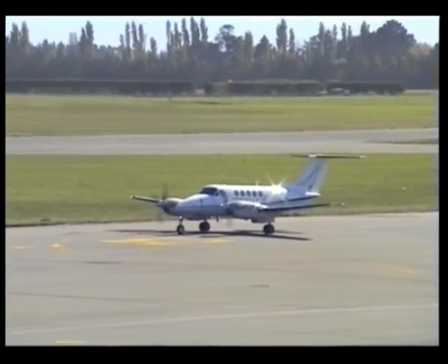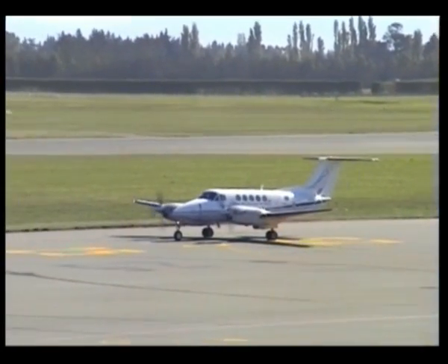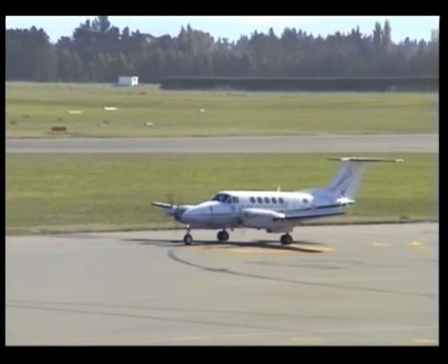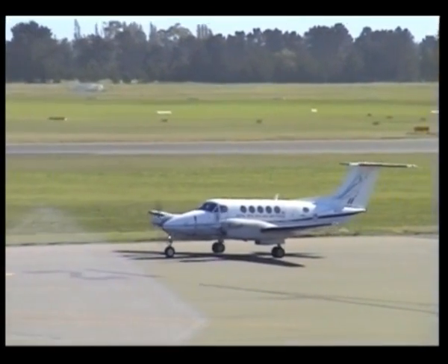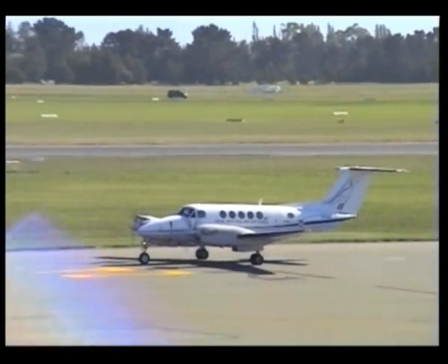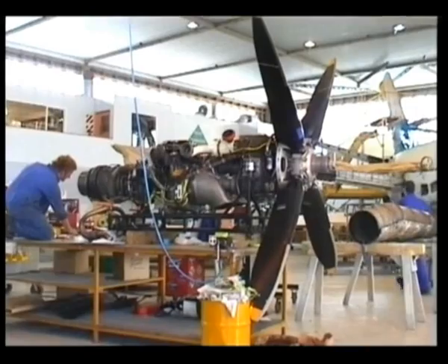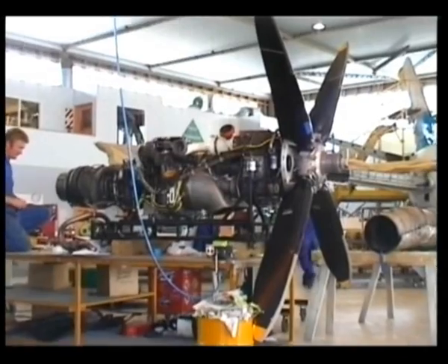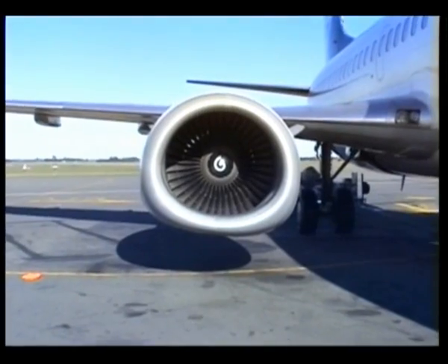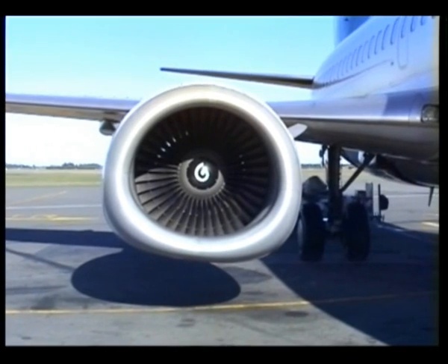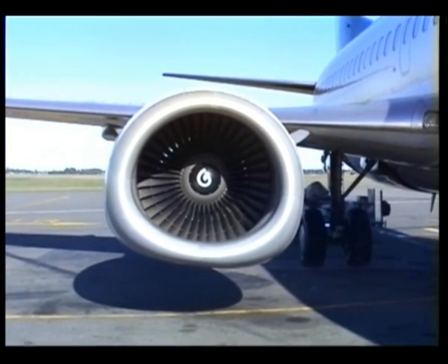Turboprop and turbofan engines are basically turbojet engines in which the combustion gases are more fully expanded in the turbine sections to develop more power than is needed to drive the compressor and accessories. This excess power is then used to drive either a propeller, in the case of a turboprop, or a multi-bladed ducted fan, in the case of a turbofan, to produce thrust.